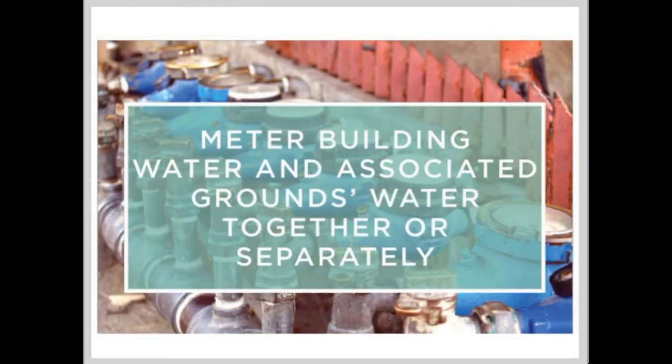There are establishment as well as performance requirements for the prereq. Under establishment, projects should have permanently installed water meters that measure the total potable water use for the building and associated grounds. Metering of any gray or reclaimed water supplied to the building is encouraged but not required. Responsible parties for this prereq include the owner, maintenance staff, facility manager, building manager, and the LEED AP.